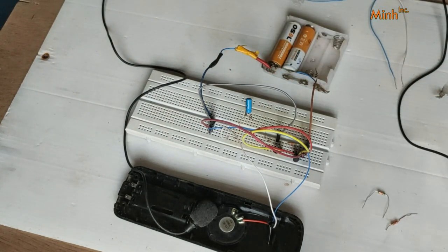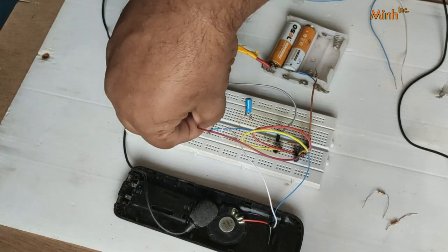Okay, so no sound. If the collector is connected to the sink directly, not to the speaker, there is no sound, because the speaker is charging and discharging through the emitter of the NPN, but it receives energy from the PNP transistor, and through that energy it is oscillating. So I'll connect it back to the speaker.